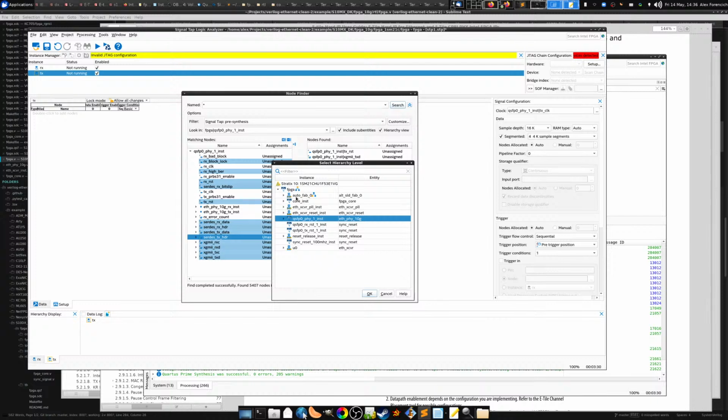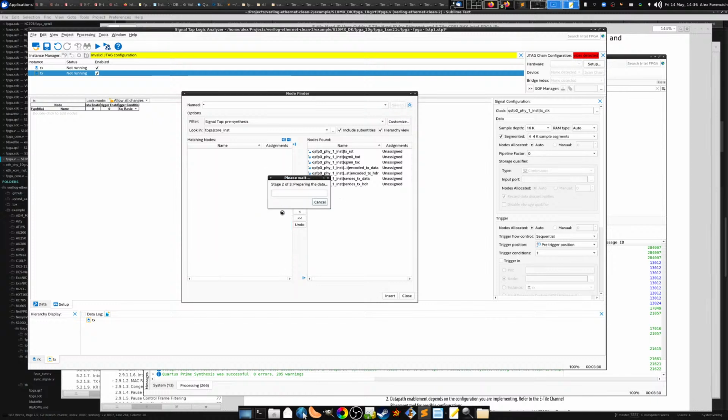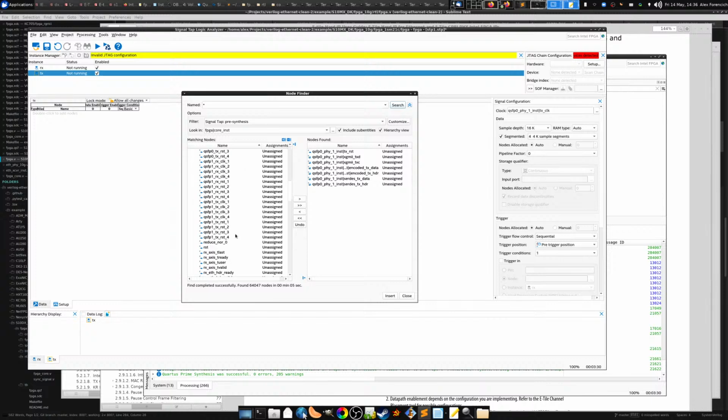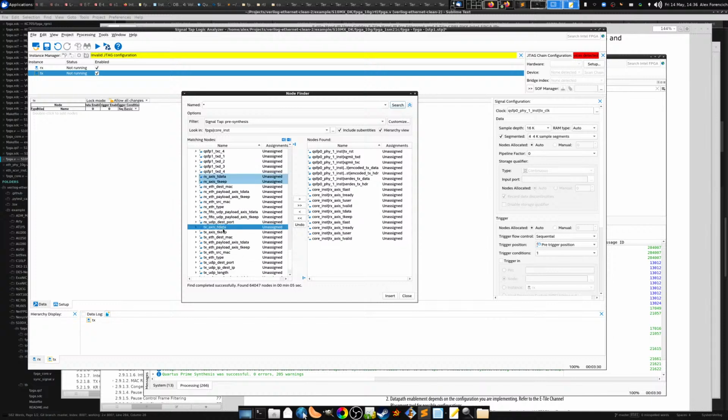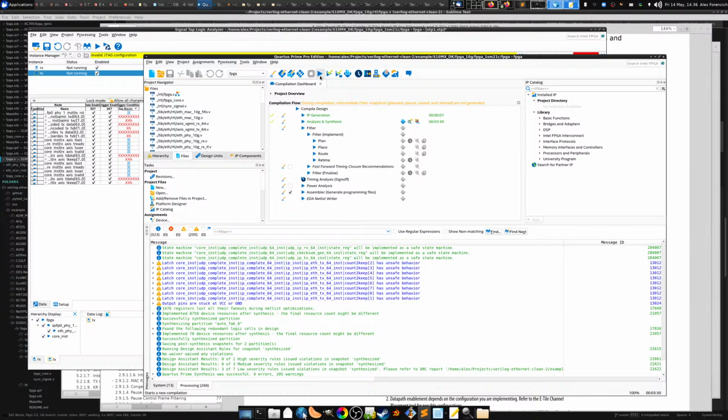And then I'm going to do one other thing. I'm going to go into the FPGA core. You remember from before, I took the transmit clock and connected that to the core logic. What I'm going to do is pull up several signals from the core logic. I'm going to see the transmit and receive data here. So start with RX. There's half of the RX, and then I've got to go down here, RX T data and T keep, and then TX everything. And then TX T data and T keep. Excellent. We'll put all those in. That looks good. So I'm going to go ahead and run that.